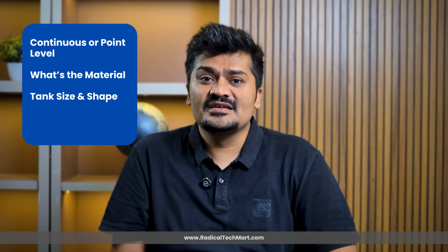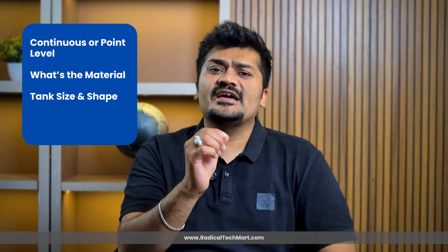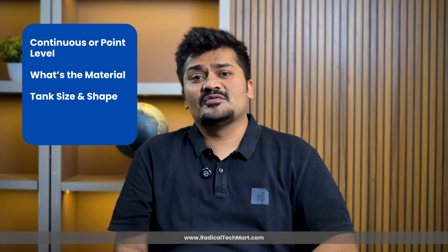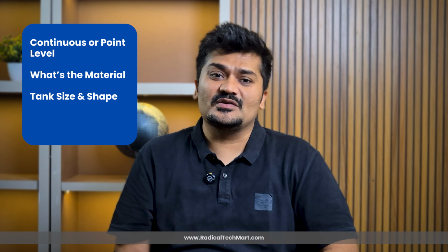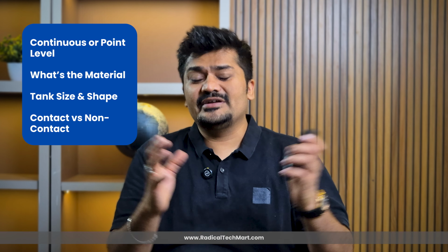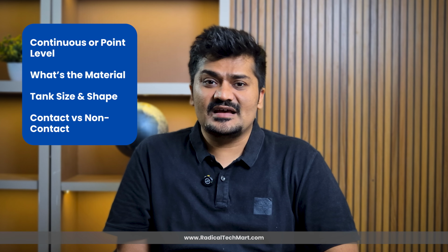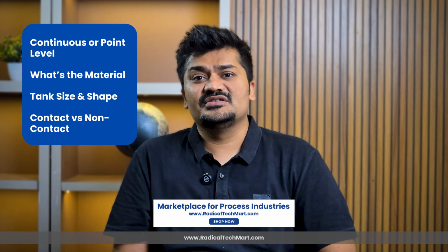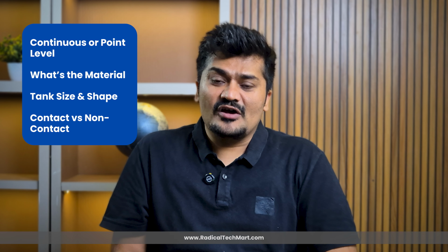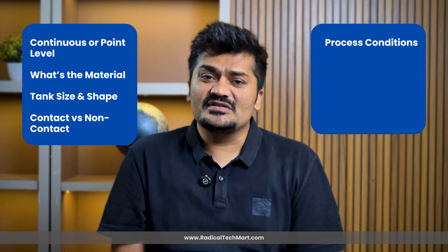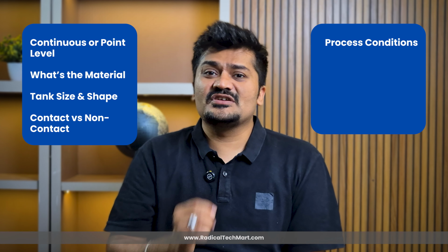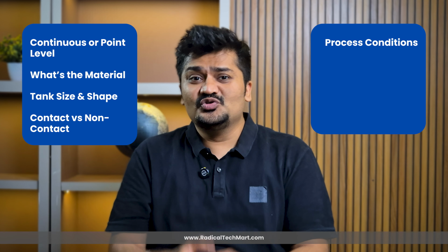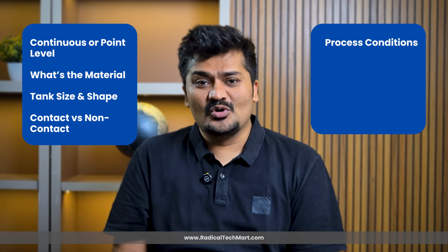Third part you need to consider is tank size and shape. Tall tank, small tank or horizontal vessel. Radar or ultrasonic is best for tall tanks, and capacitive for bins or silos. Fourth one that you need to consider is contact or non-contact. Non-contact sensors are radar or ultrasonic, and the second is contact sensors, that is float or GWR. This is better in small tanks or foamy liquids. Fifth part that you need to consider is process conditions like temperature, pressure, and whether vapor or foam is present or not. Use radar for extreme environments and use a submersible sensor in wells or boreholes.